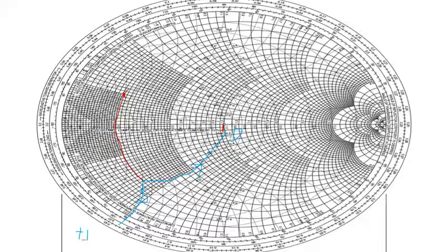When it is plus J2, the formula says it is going to be destination minus source. Destination, if you remember, I had told last time also, this destination is going to be real value 1 and imaginary 0. So the formula says 0 minus J2. So it will become 0 minus J2, that is minus J2. Now that is the value of your inductor. This is a parallel inductor.